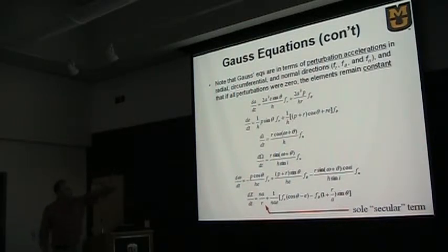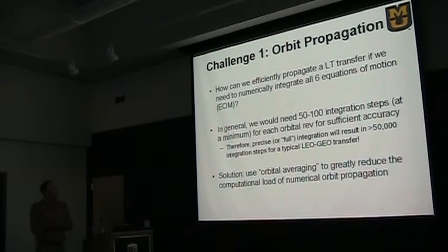And everything's got an F on it, except one term. There's a single secular term. That deals with this last equation, because the capital E is an angle. So that's telling us where it is in the orbit. And there's one term that does not involve thrust.